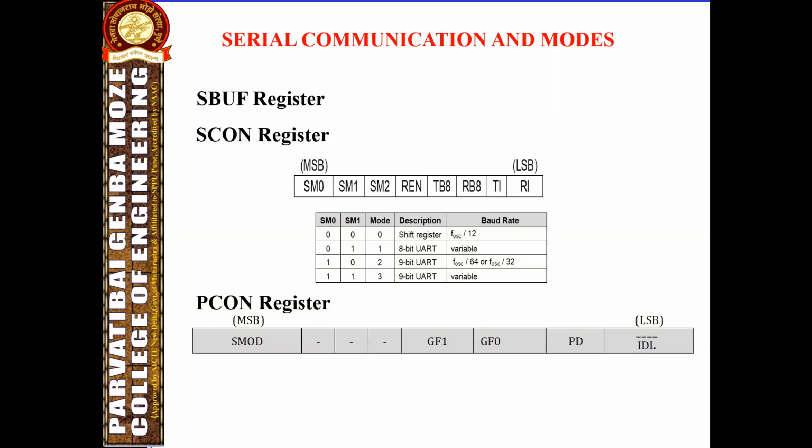Serial communication is slower than parallel communication. If the data is to be transmitted on a telephone line, it must be converted from ones and zeros to audio tones, which are sinusoidal signals. This conversion is performed by peripheral devices called a modem, that is, modulator and demodulator. When the communication distance is short, the digital signal can be transmitted on a simple wire and requires no modulation.